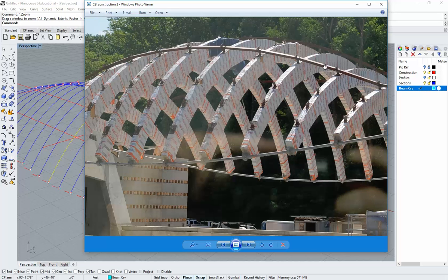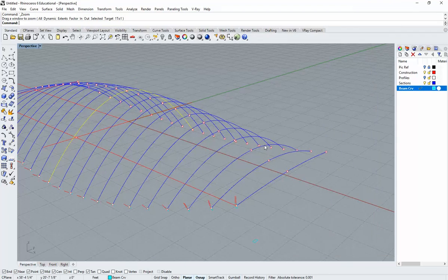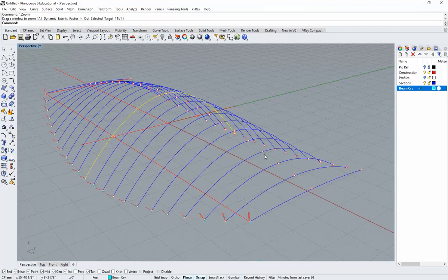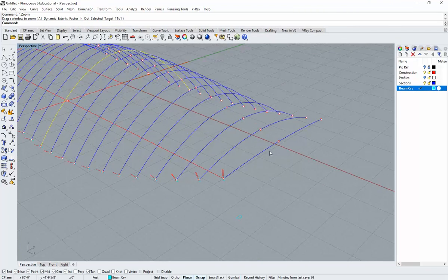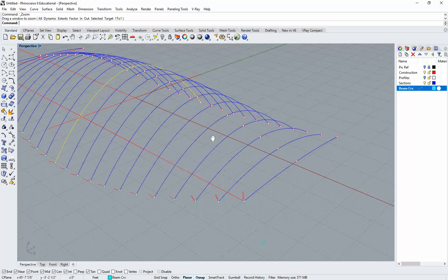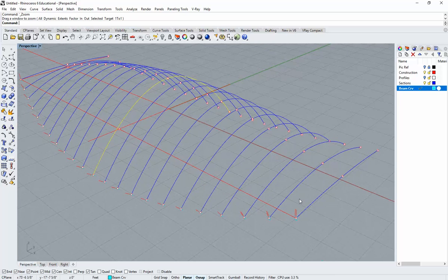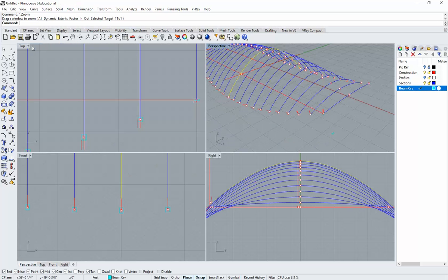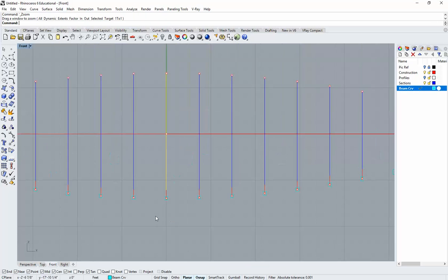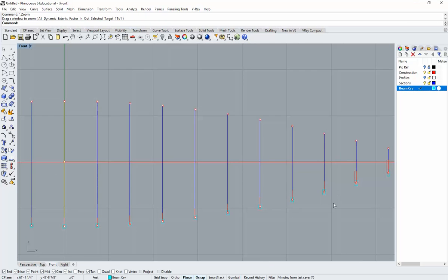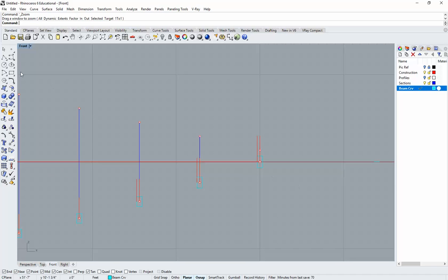So that means we need to set a different section curve up at the top of our model along these points. And that's easier because we don't have to orient those. These can just be drawn basically in the front view. So what I'm going to do is head over to the front view, and in my beam curve layer over here somewhere, I'm just going to draw a rectangle again.